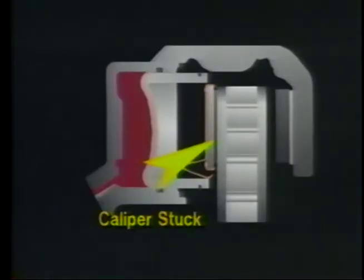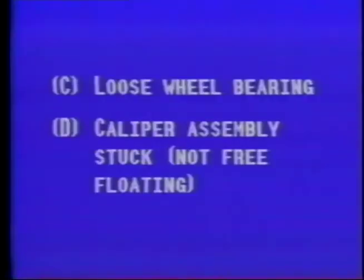Instead of having one piston for each brake pad, a single piston applies pressure to one pad. The caliper assembly floats freely. When pressure is applied by the piston, this pushes the brake pad against the rotor. When contact is made, the caliper moves with an equal force until the other brake pad contacts the rotor. If the caliper assembly was stuck, only one brake pad would wear. The correct response, D.